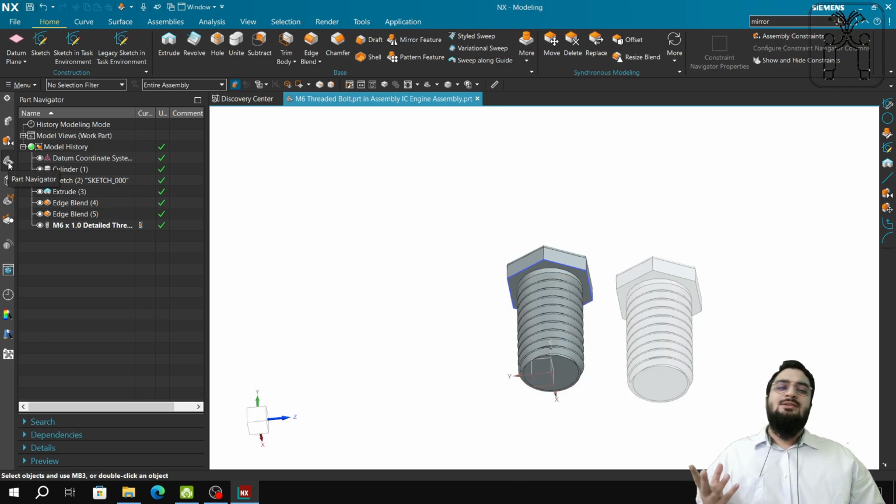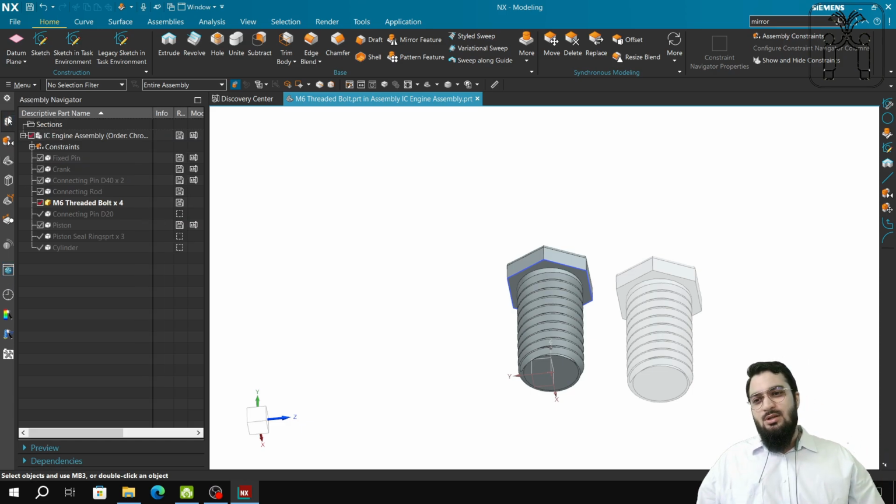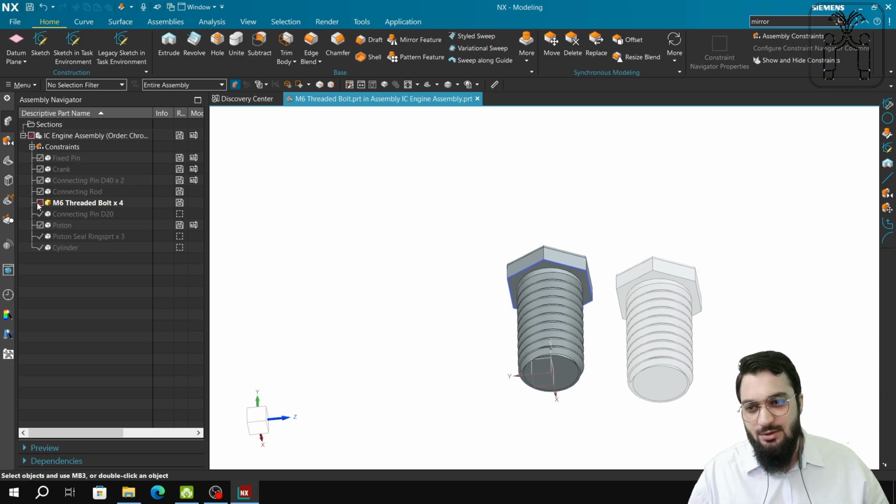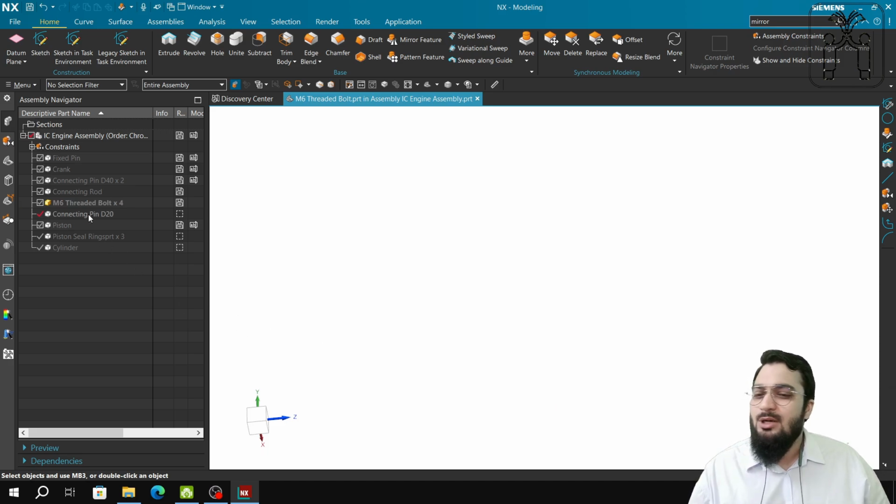That is all. And the main thing in mechanical engineering which we have studied, the thing which I think none of you would ever forget, is that sharp edges lead to stress concentration, which leads to failure, and soft edges or edge blends or edge fillets work much better. Edge blends, or chamfer or fillet, allow it to reduce the stress concentration, thereby reducing the chances of failure. Now, coming to the connecting pin.